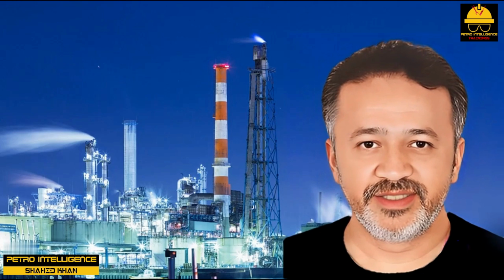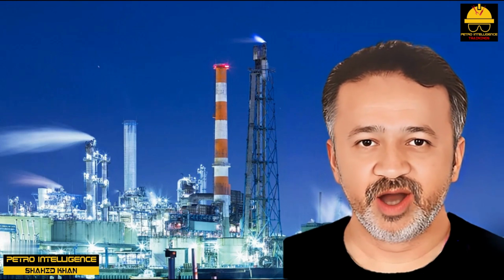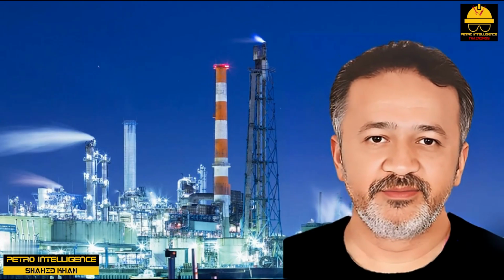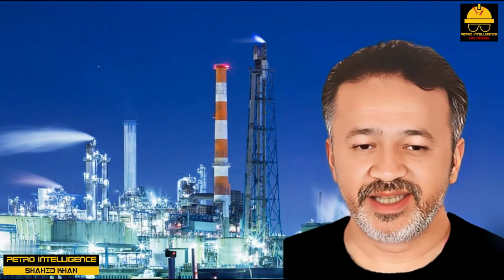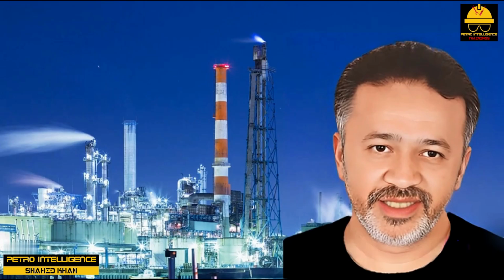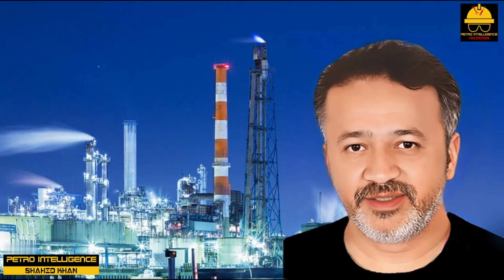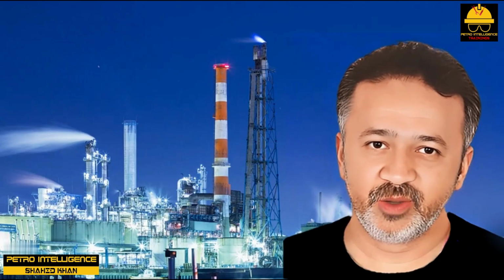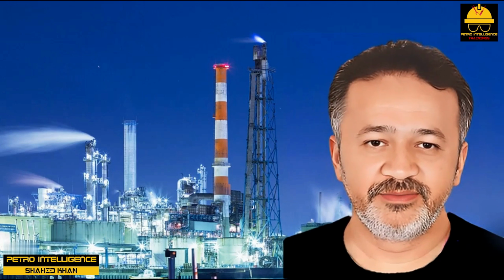This may happen if the condenser outlet line is undersized. Let's say that the pressure drop due to piping friction losses in this line is 10 psi. The refrigerant is isobutane. The isobutane cannot flash as it enters the refrigerant receiver. The reason it cannot partially vaporize is that there is no vapor outlet from the receiver. If it were to vaporize, it would slightly increase the receiver pressure. This would push up the liquid level in the condenser.